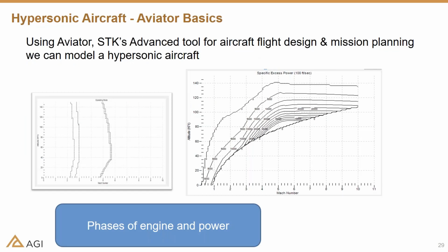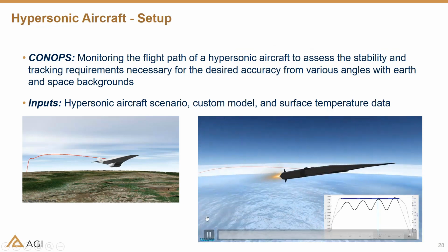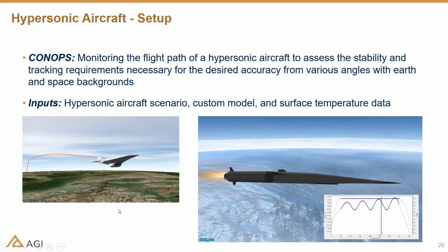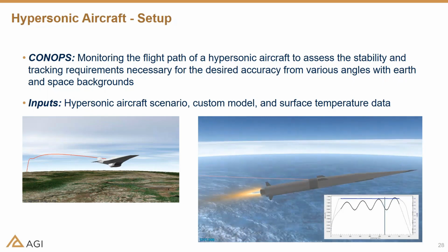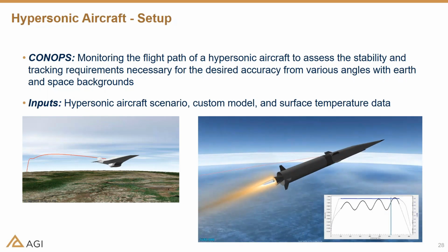Hi, everybody. I'm Tom. A lot of this stuff is what I've been working on for the last 20 years or so. Pat showed you that airplane that's flying up and down, or we might say it's bouncing off the atmosphere. That's actually an aircraft that's flying a constant angle of attack. And because of that, it boosts up, and because it's flying a constant angle of attack, it will fly what we call a phugoid flight path. And so that's what you see there. And I believe it's about 140,000 feet or so, so it's up there where the air is very thin.